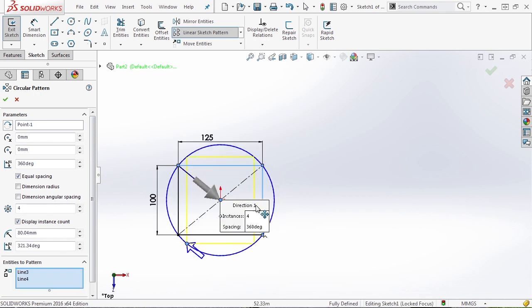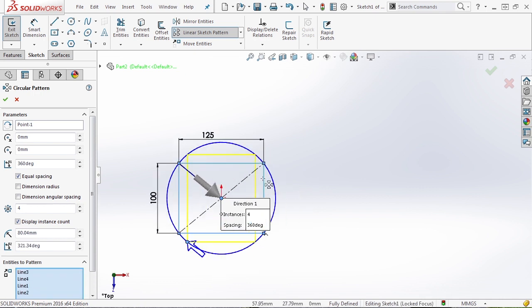So you'll notice as I select these lines, it's pretty interesting. It's taking these lines and it's basically rotating them about, and we're creating that rectangle in another, essentially, orientation. If we make 2 instances, you'll notice it looks like nothing happens. That's because we're traveling 360 degrees and we're making 2 instances. It's basically overlaying them. If we change this to 180, you notice that it does the same thing because we've essentially taken this and simply flipped it upside down. But if we go intermediate, 90 or 270, we're basically taking the original shape and rotating it 90 degrees.